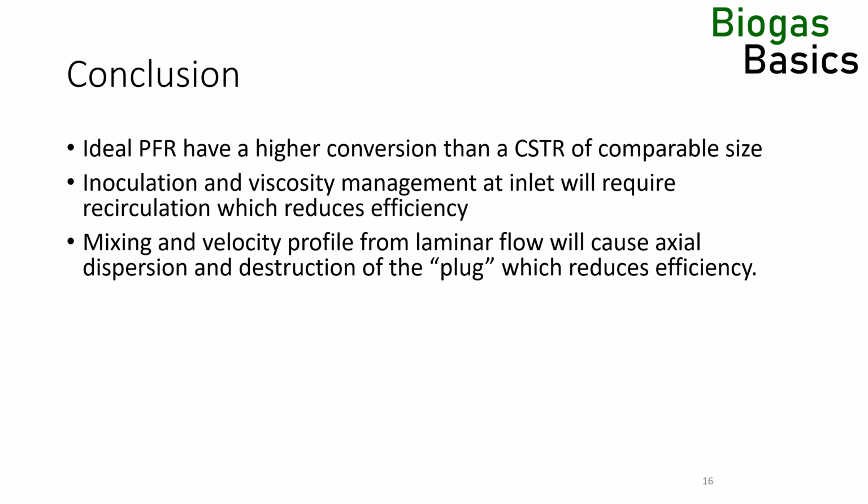The requirement for a plug is that all fluid elements travel through the reactor with the same axial velocity, but the flow conditions in a flow reactor in the AD industry are laminar, and laminar flows are characterized by a parabolic radial flow profile. The maximal speed of a fully developed flow profile is twice the average speed. It is impossible to maintain a plug. We should really call them flow reactors and not plug flow reactors.